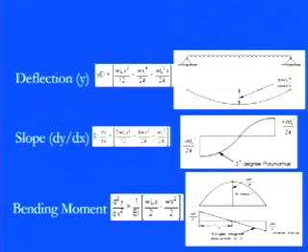So you can see that the bending moment variation is exactly similar to the deflection, because at these two extreme corners of the simply supported beam there are no bending moments, but it has a maximum value where, because of the UDL we already evaluated, and you can see this in the figure corresponding to the equations, we have the maximum value of bending moment at the center point, which is equal to WL square by 8.